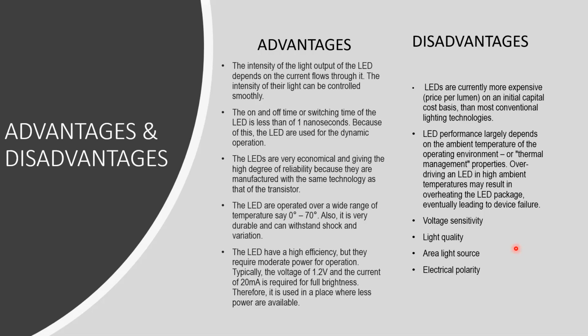Disadvantages. LEDs are currently more expensive on an initial capital cost basis than most conventional light technologies. LED performance largely depends on the ambient temperature of the operating environment or thermal management properties. Overdriving an LED in high ambient temperatures may result in overheating the LED package, eventually leading to device failure. Also, we can mention voltage sensitivity, light quality, area light source, electrical polarity, etc.